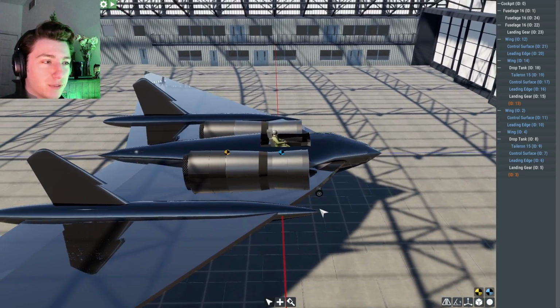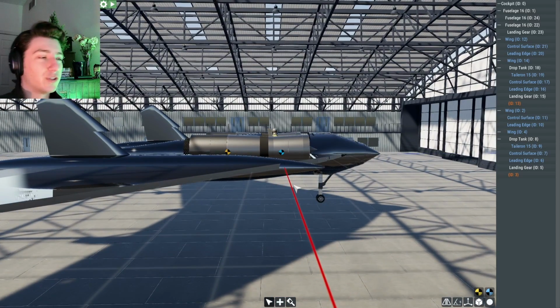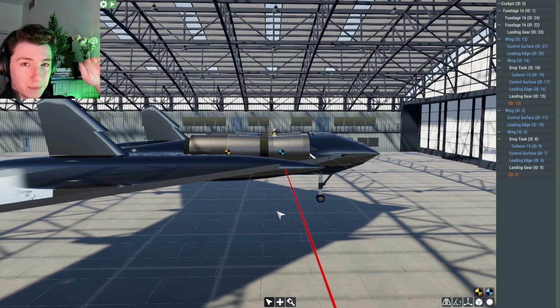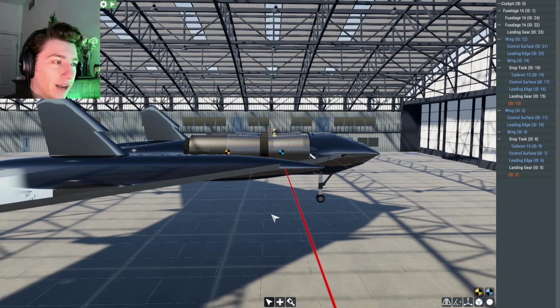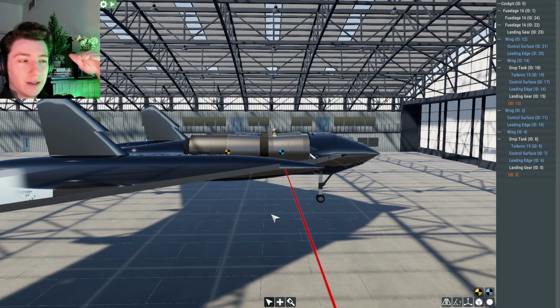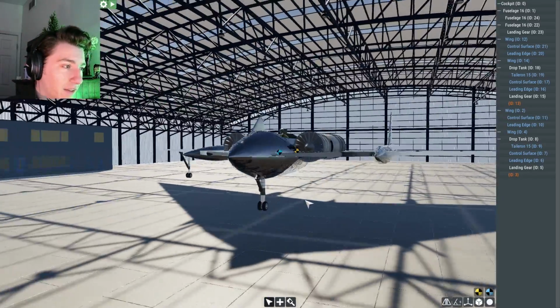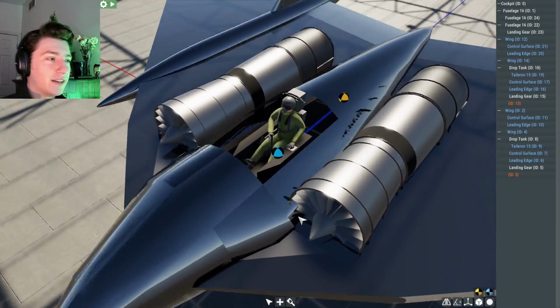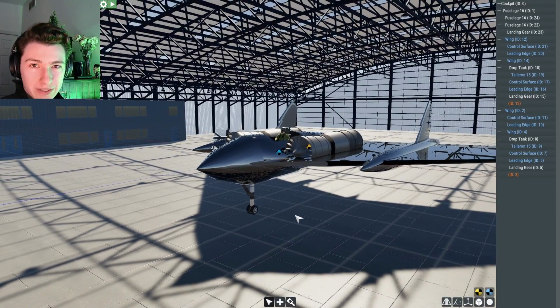This causes problems for a few reasons in conventional aircraft. For one, this leads to an aircraft that is what we call unstable, which basically means if I tell this aircraft to pitch down, it's going to continue to pitch down harder and harder without any more input from me. Whereas with a conventional aircraft, you tell it to pitch down, it pitches down, and then tries to return to normal level flight. Now, this is a problem because if you're the pilot, this guy holding the joystick right here, you are not going to be able to control this thing.